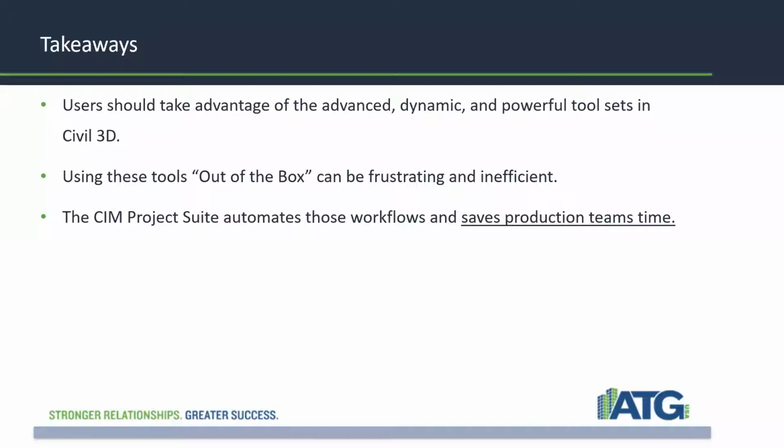When I go through and create my plan and profile sheets with the out of the box method, the view frames, once I create my sheets, I'm done. That's static. I don't have the opportunity to change that information. If I use the sheet generator tool though, and all of the steps and all of the tools in that workflow, I can update that information dynamically throughout my project from wherever that major change went forward. And that's a lot of time that I get to save, especially at the late stages of my project.